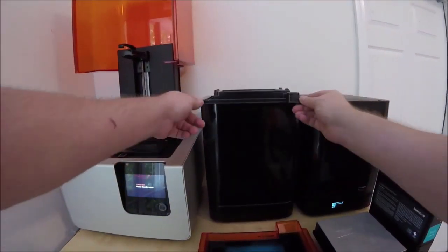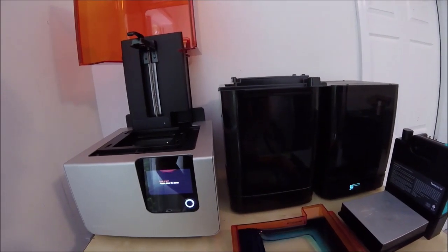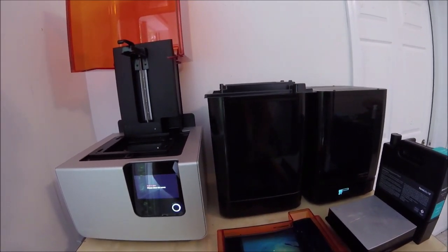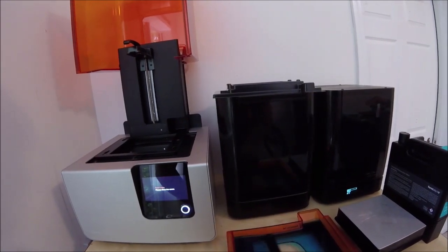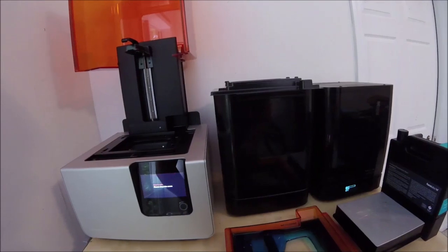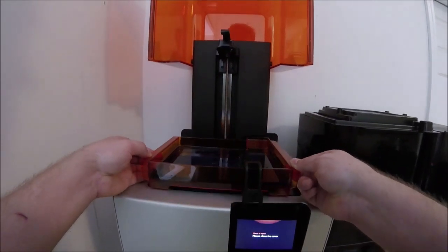And you can see here this resin tank is already filled with tough resin. I usually like to give the resin a couple swipes with the wiper just to make sure it's all stirred up. Also to make sure that the bottom of the tank doesn't have any cured resin on it, so you can see the bottom of the tank is very clear here. This just ensures your resin's in good shape and ready to be used. We'll take the resin tank and put it into the printer.